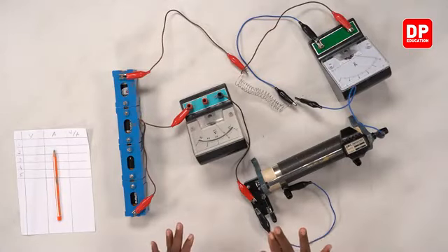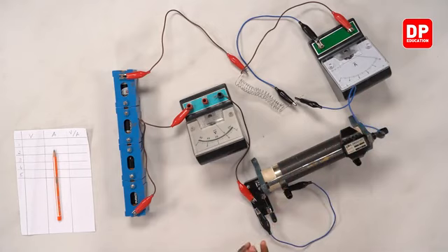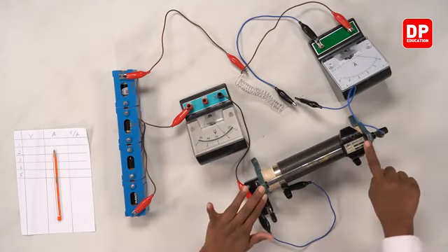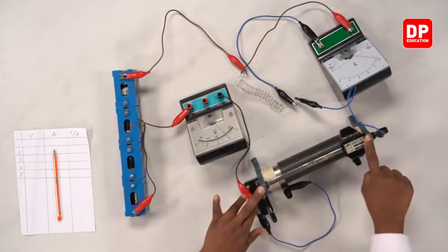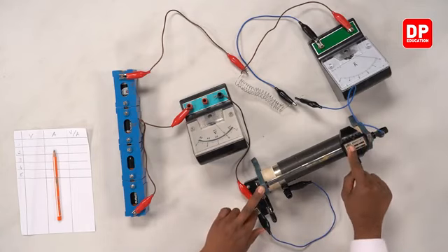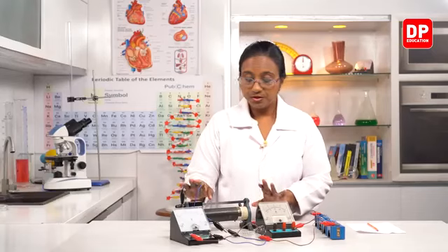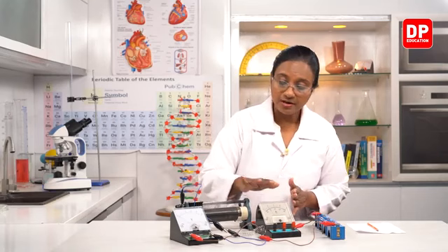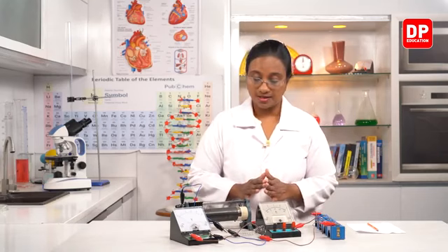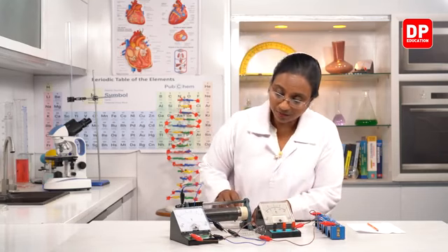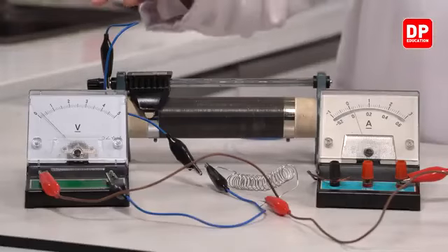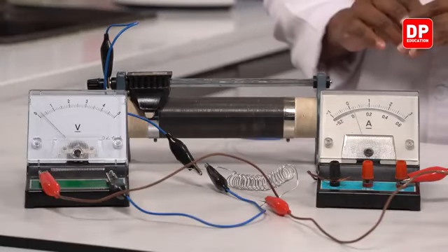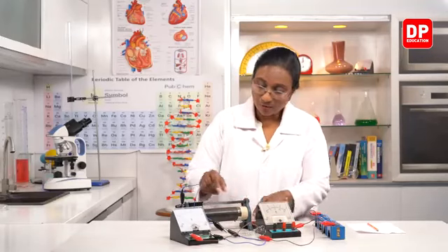So now here you all can see, students, I have set the ammeter, voltmeter so that you can see the readings, and here I have pushed this knob to the extreme end. So the resistance is very high at this point. So now when I close the switch, the circuit will become complete. Have a look at the voltmeter and ammeter readings. So here I am going to close it. There is no deflection because the resistance is high. There is no current flowing through the circuit. So I'll open the switch.